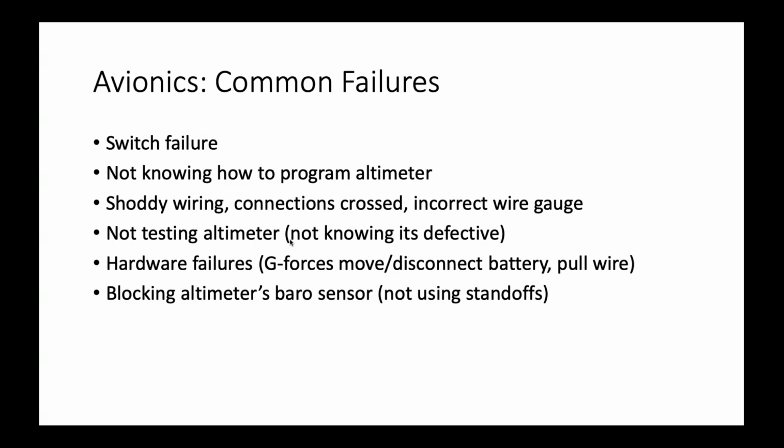Usually altimeters, I think the StratoLogger, come with standoffs. Standoffs are little plastic spacers that you put in between the altimeter and your mounting surface when you screw it down. That allows a little space around the barometric sensor so it has access to the air, and then with your vent holes, it'll have access to the outside atmosphere.